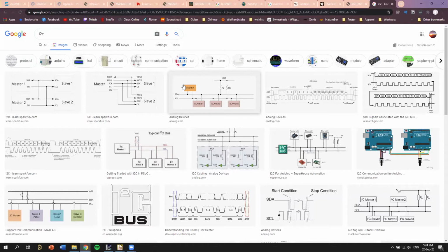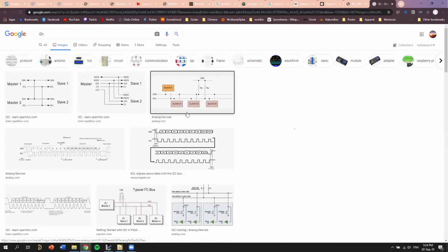Typically you'd have a chip select, an independent chip select to say, all right, I want to talk to this one, and it activates each of them as you cycle through. But with I2C, instead of having 10 dedicated lines that go to each of 10 sensors, you only need 2 lines to talk to all of them. That's what a communication bus generally does. You can talk to a lot of things over a few connections.